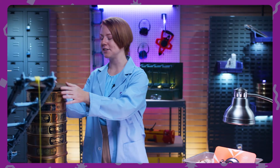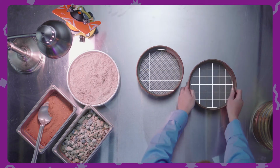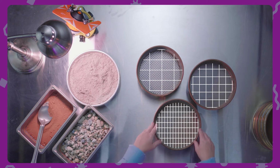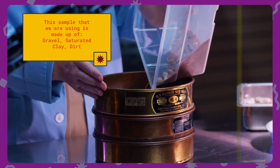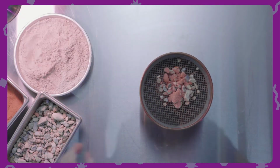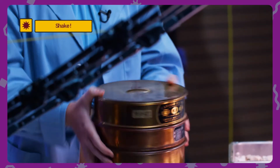We have an example of a sieve stack here, and we can see that in the base of each plate, there are different wire meshes, which collect the particles that pass through. Let's say that we have a soil sample from on-site. We can pour it into our top sieve, place the lid on top, and then give it a good shake. And naturally, the particles that are small enough will fall through.